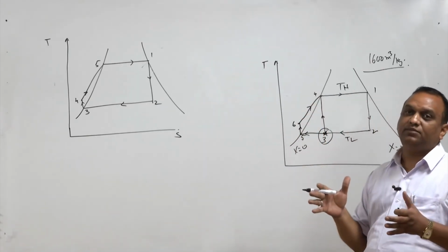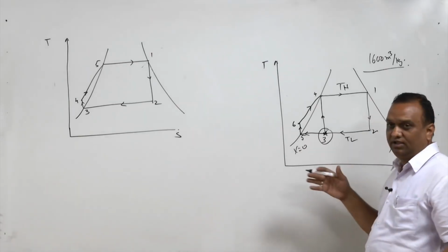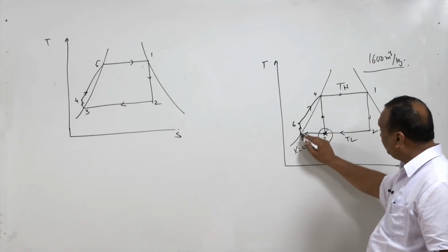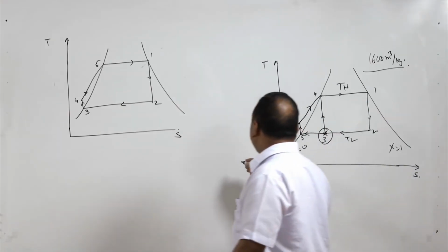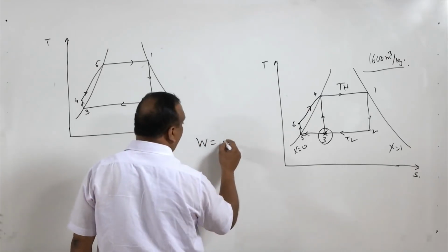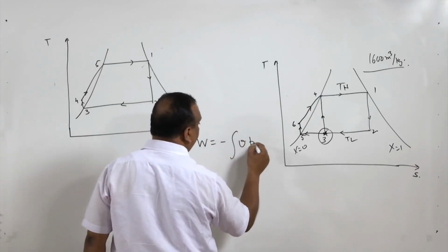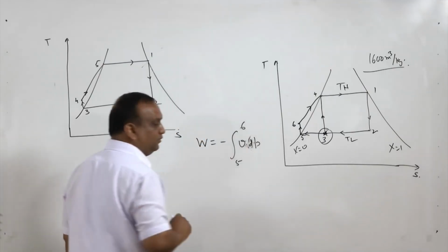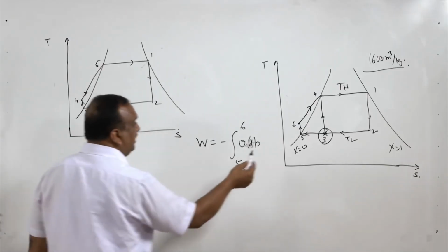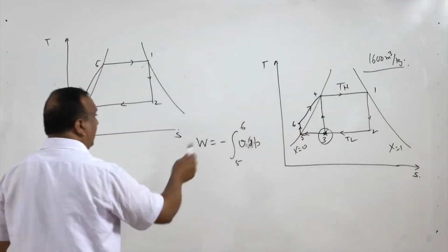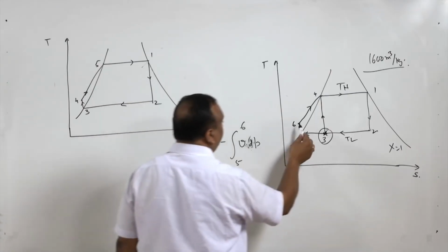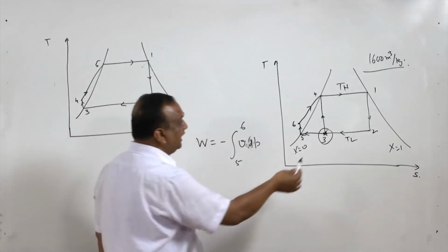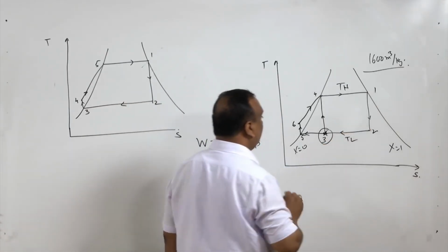So when all the steam is condensed in a condenser, the volume of the fluid is reduced drastically, and it is very easy to compress, because here the work consumed will also be less, because it is going to be VDP from state 5 to state 6. Now, this high pressure liquid will be sent to the boiler, where heat exchange from state 6 to state 4 and state 4 to state 1 will take place. From state 1 again the fluid will enter the turbine and the work will be produced.